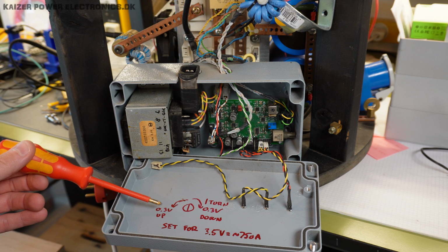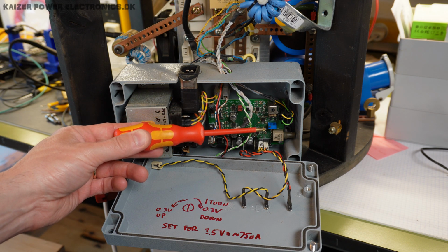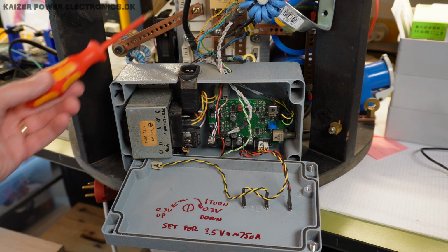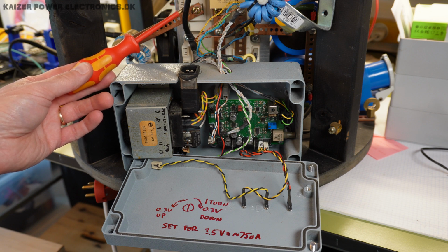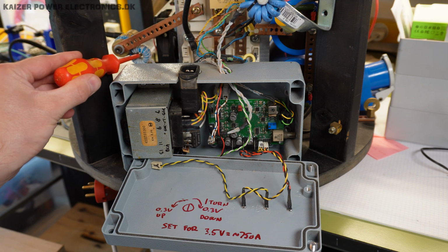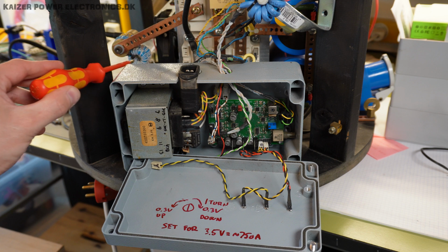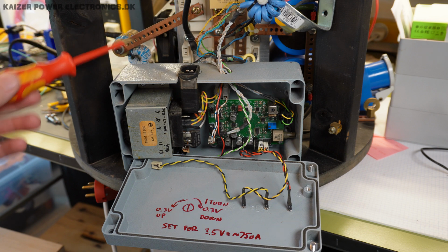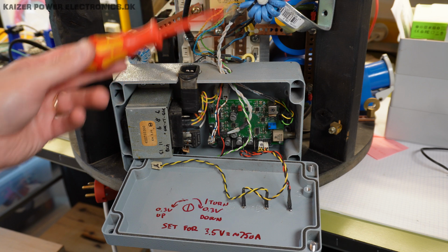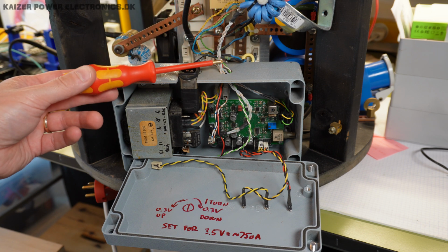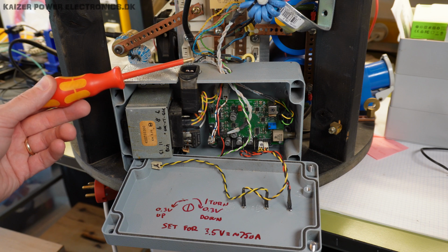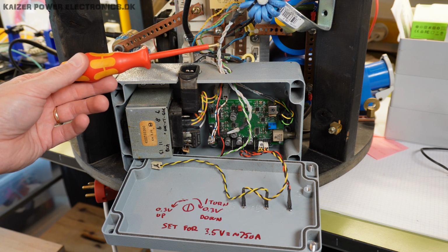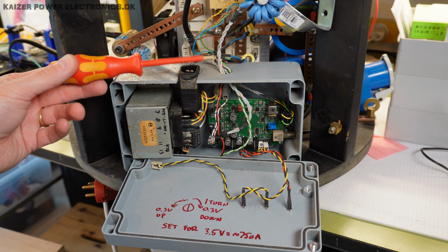Now we can see here that it uses a 10-turn overcurrent detection setting, and I have set it for 3.5 volt for 750 amp on these SKM 200 IGBT bricks. The feedback and current measurements, or the overcurrent detection, use two 1:1000 ratio current transformers sitting over here, and we have a single GDT with 4 outputs and a single primary. We already know that we will have to change the current transformer ratio, and the GDT will have to be rewound into 2 separate GDTs.